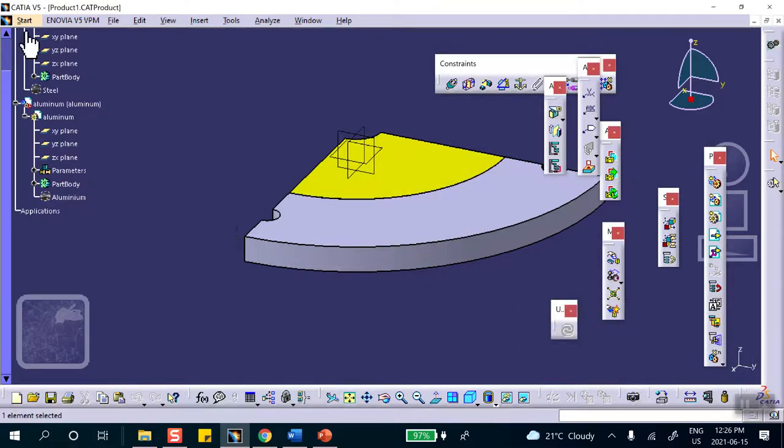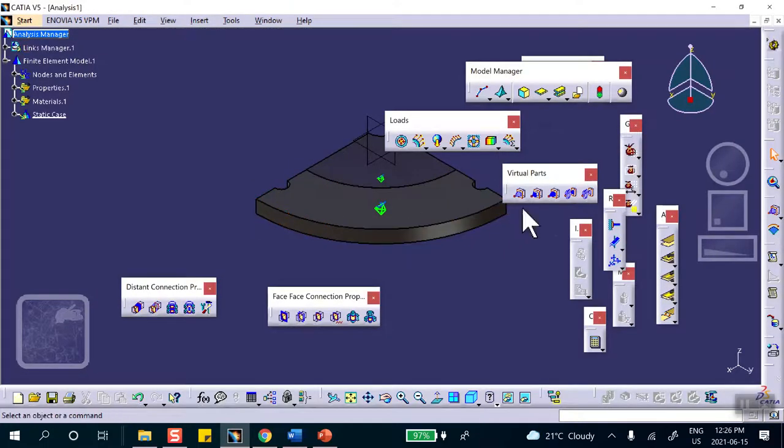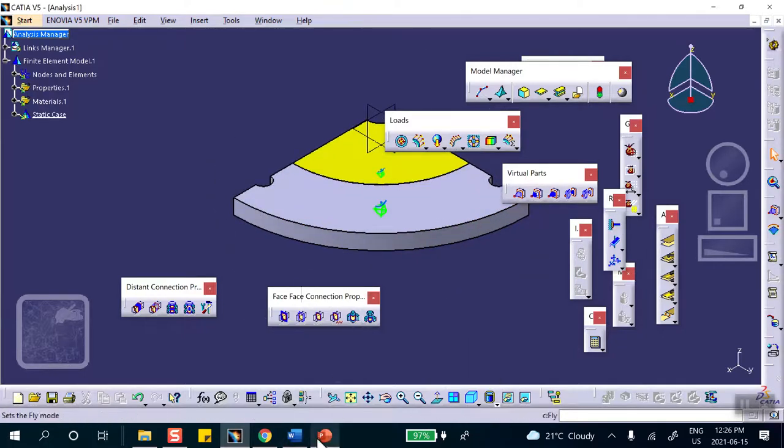All right. Now we're going to go to generative structure analysis, get these two solid parts. Immediately it meshes both, which is fine. We're going to keep the sizes the same. And let me change the rendering here, by the way. Okay. You are asked if you may have a local mesh refinement about the interface.